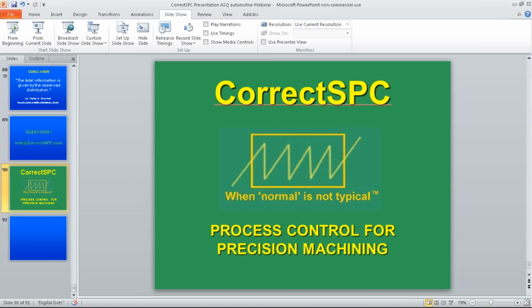I would use an X bar and R with a sample size of 1 and the range being the high and low reading of the part measured. What do you think? Well, an X bar indicates using an average, and I don't calculate any averages with this because there's no point. The average doesn't do anything for the distribution that we're looking at. So I simply take one part, measure around it, get the high and low, and then measure consecutive parts and watch the tool wear effect on them and make adjustments accordingly. So I don't use averages at all. There's no real benefit to them.